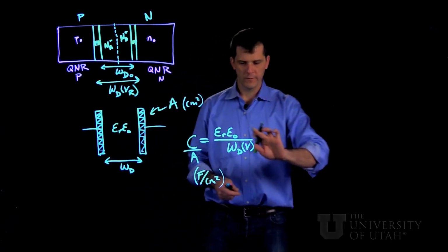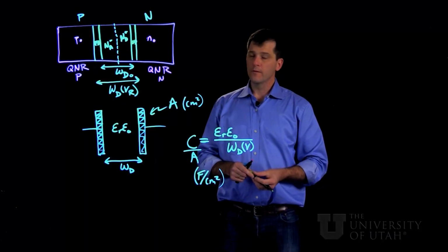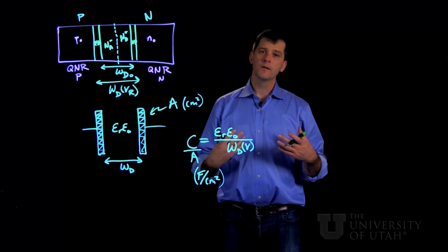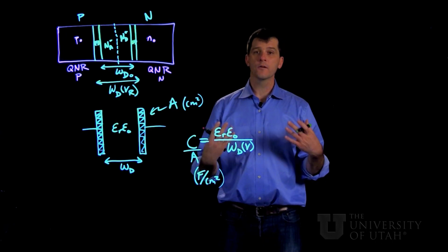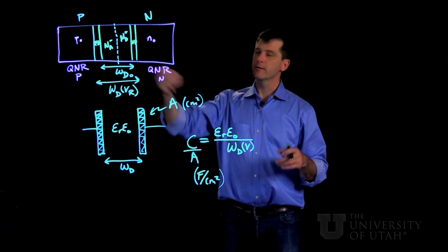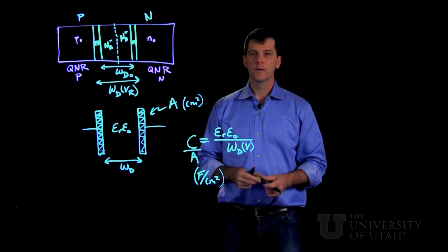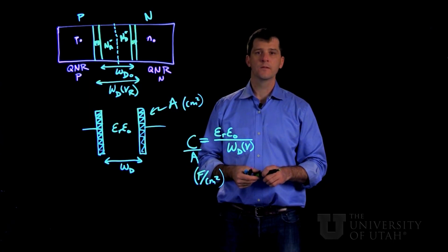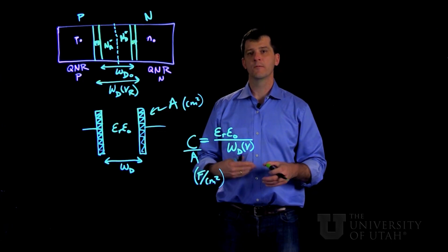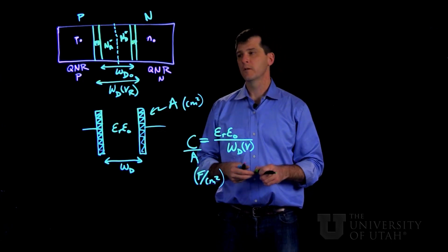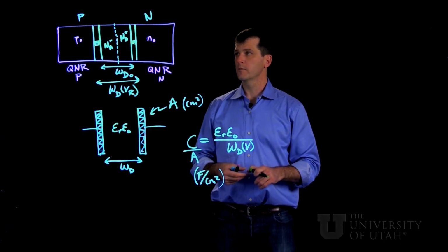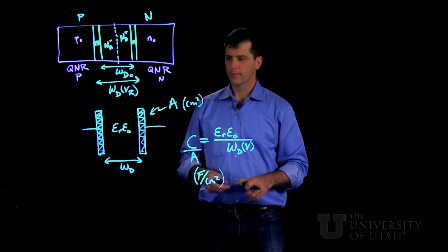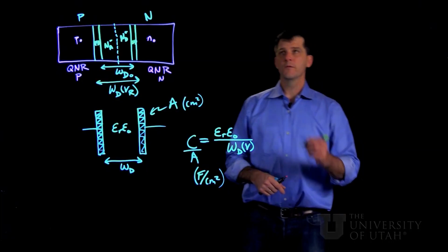So it's quite a simple expression. Now, what this allows us to do is to actually adjust the capacitance in a circuit on the fly by applying a voltage to a PN junction, to a diode. So one function of a PN junction in circuit design would be for a varactor, or a variable reactive load capacitance. So now let's look at a simplifying case.